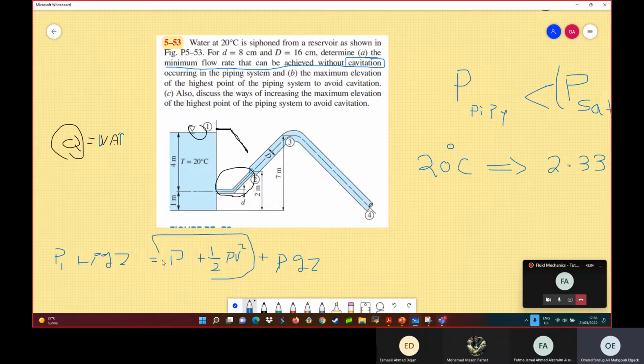So look at those. When I go from the left side of the interface to the right side, I'm increasing the cross-sectional area, and therefore the velocity will decrease. Now, when the velocity decreases, the pressure will increase to compensate for this reduction. And I'm not changing the elevation because I'm just to the left and just to the right of this interface.